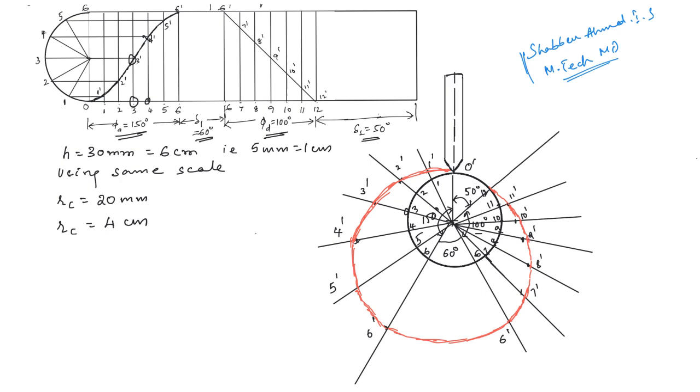So this is the shape of the cam for the given displacement of the follower. The ascent is with simple harmonic motion and the descent is with constant velocity. So that is how you draw this cam profile. You practice this on a drawing sheet using a mini drafter. Without the drafter you can't do it, so you do it properly using a mini drafter and drawing sheet.